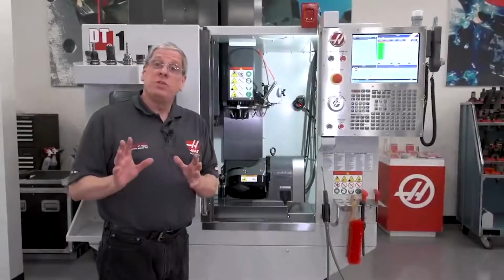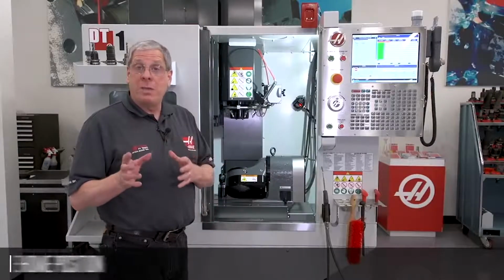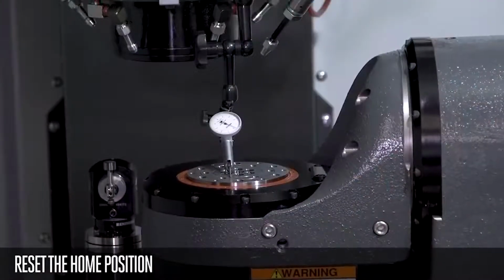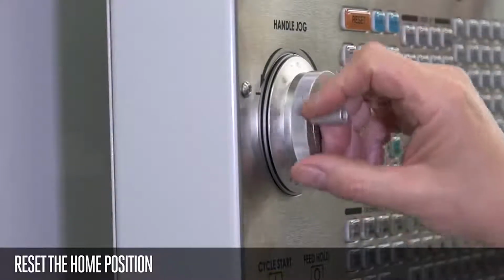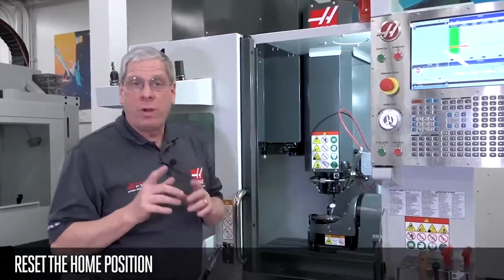So I zero return the machine and it's obvious that the tilt axis is not flat. So I'm going to get my indicator out, I'm going to flatten that up, and I'll show you how to reset the home position. Okay, I've got my platter indicated nice and flat, right where I want it.